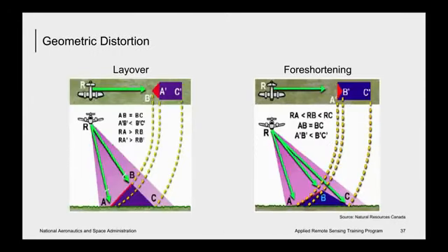Similar to distortions encountered when using cameras and scanners, radar images are also subject to geometric distortions due to relief displacement. This displacement occurs perpendicular to the flight path. However, this displacement is reversed, with targets being displaced towards instead of away from the sensor. Radar foreshortening and layover are two consequences which result from relief displacement.